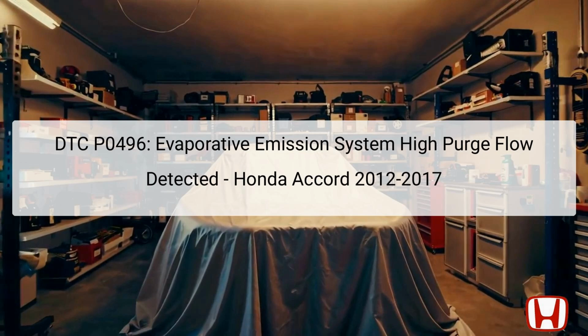When the EVAP canister purge valve is functioning correctly, it allows fuel vapors to be drawn into the engine for combustion, aiding in emissions control. However, when this valve becomes stuck open or experiences abnormal flow, it triggers the P0496 code. The issue can lead to increased emissions and potential engine performance problems. Understanding the function of the components involved is essential in diagnosing and rectifying this issue effectively.